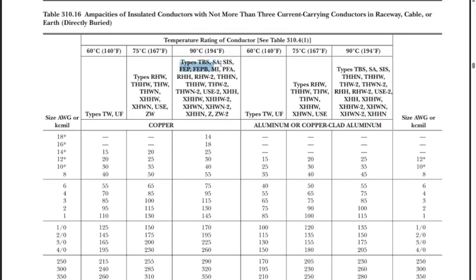All of these little abbreviations here, all of these are insulation types. All right, these little insulation types mean things like some of these insulations are rated for very high heat. That is where you see the TH, thermo heat. All right, some of these are for wet location. This is where you see these W's. All right, some of these are rated for oil and chemicals and etc. So these insulations do protect the copper inside the wire. But here is the temperature ratings up top.